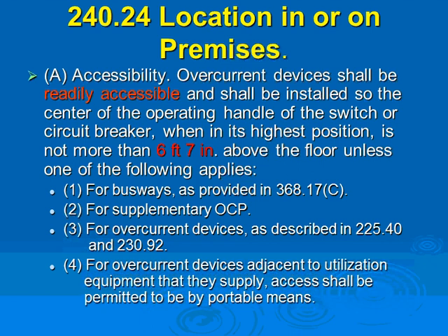For example, supplementary overcurrent protection device. So I decided to fuse this light. Does it have to be 6'7", the fuse or circuit breaker to this light? Supplemental. No. Busways, your busway is set at 25 feet above the manufacturing floor. You can have other means of reaching these disconnects, the sticks and so forth. So there are a few exceptions for the overcurrent protection device.